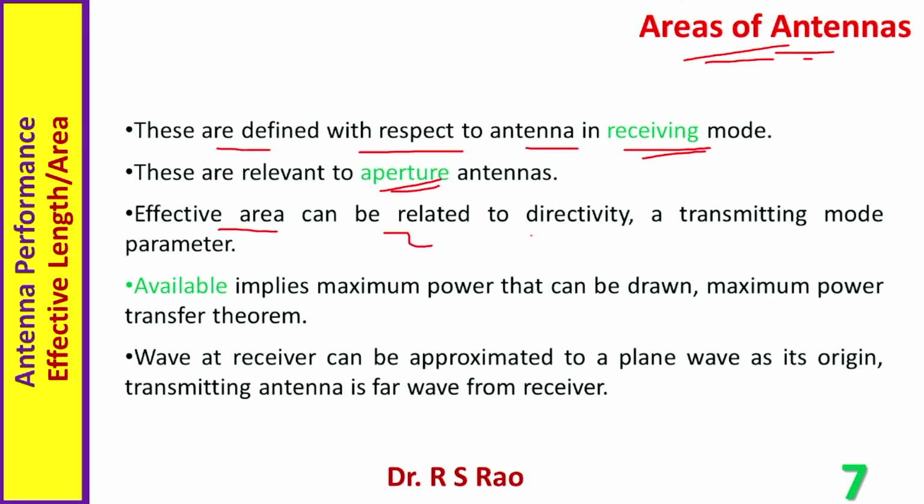Effective area can be related to directivity, a transmitting mode parameter. In the definition, we come across the term available. It implies the maximum power that can be drawn, an implementation of the maximum power transfer theorem.